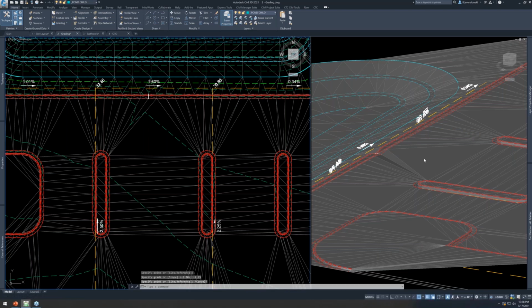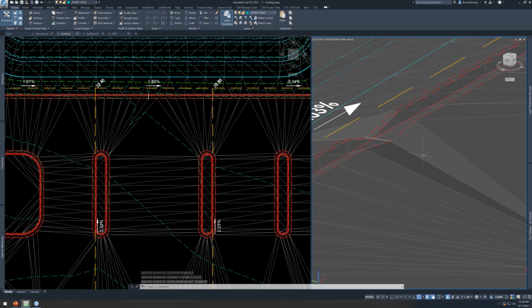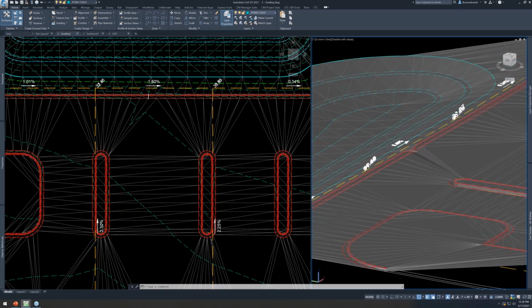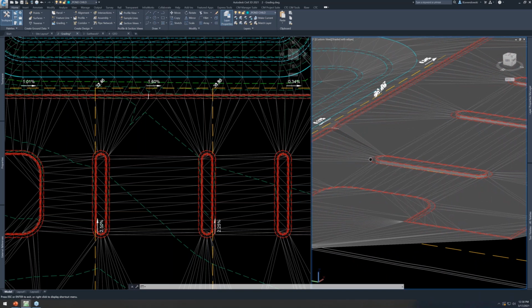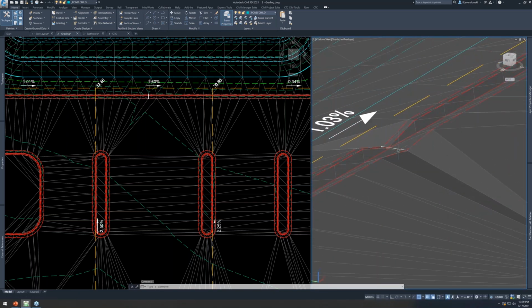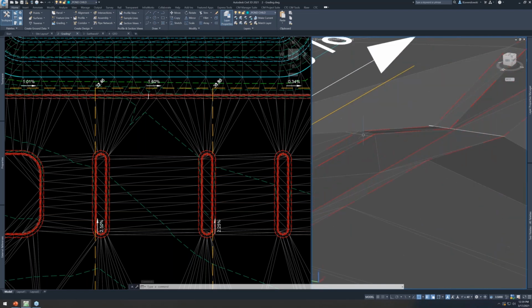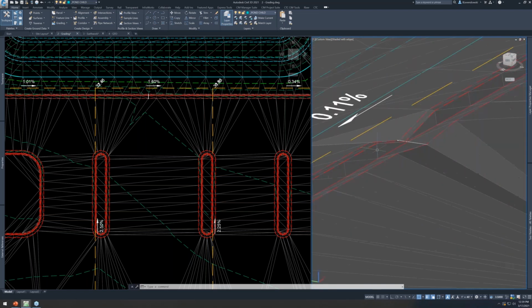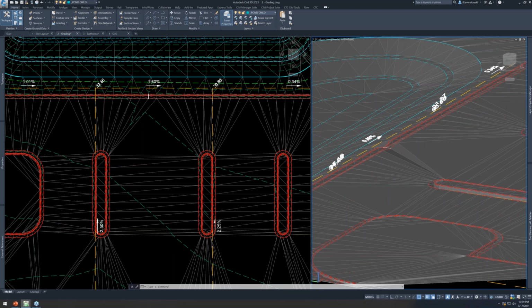And if you look over here in model view, you'll see things are kind of a mess, right? Everything's kind of cut all over the place. The curb is too high. Now the gutter lines moved up and down with it. The curb cut moved down with it, but now I've got like a 1 foot tall curb. So you've got to think of which feature lines are sticking to your parking grid surface. It's those gutter lines and that curb cut one. Those already moved up and down accordingly.